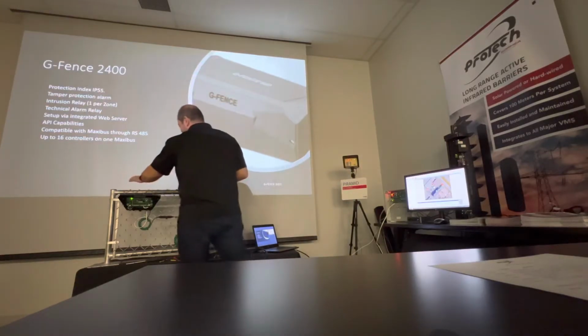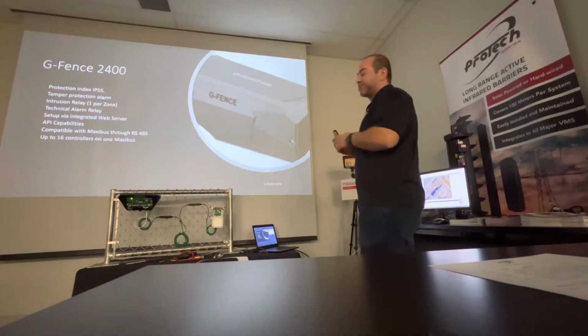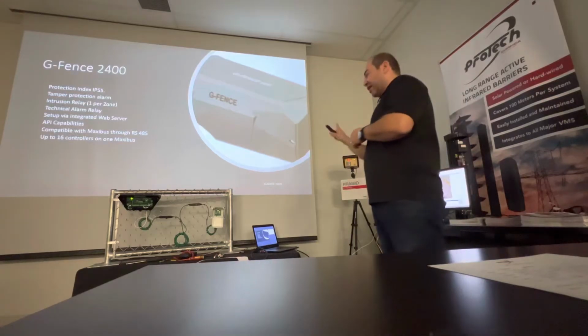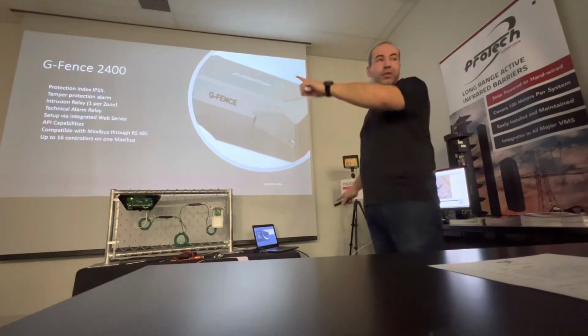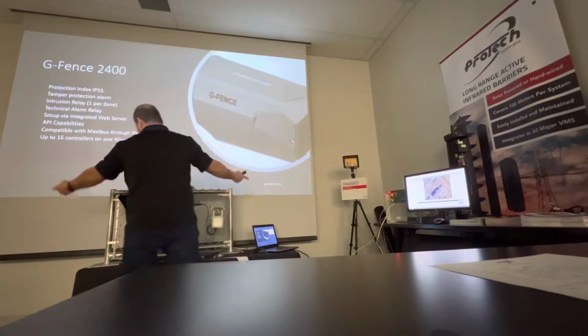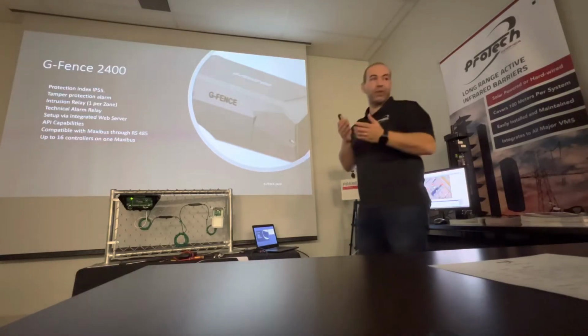Okay, so I repeat. The control unit 2400 can handle up to 600 meters. One way? Sorry? Like it can have one loop, 600 meters? No, it will be 300 meters on one side, 300 meters on the other side. Oh, so 600 meters on both sides. Here. So 300 and 300. Each 100 meters, it's split with the link box.